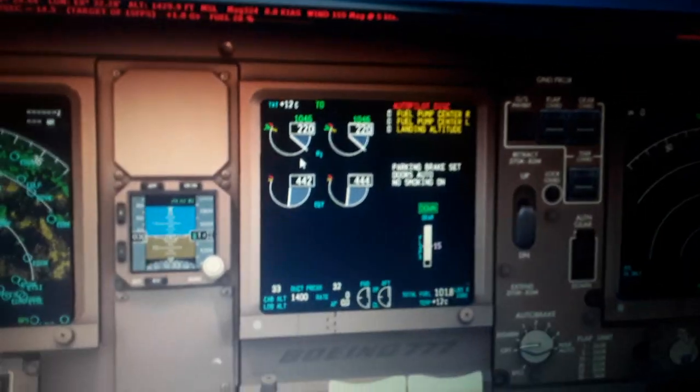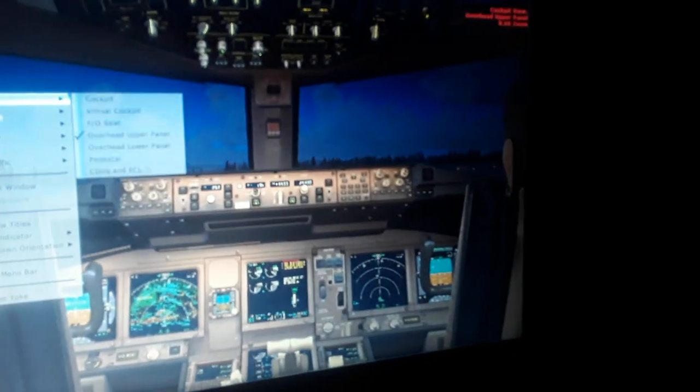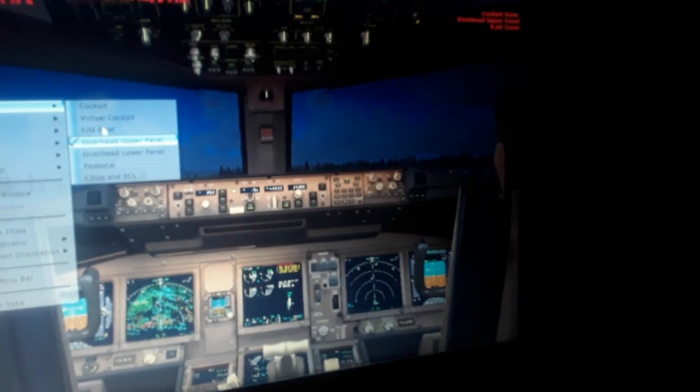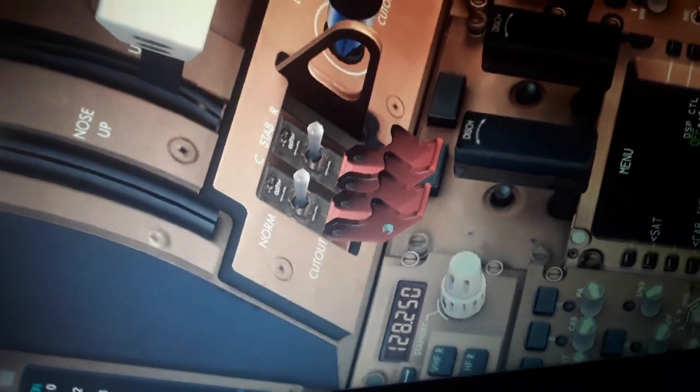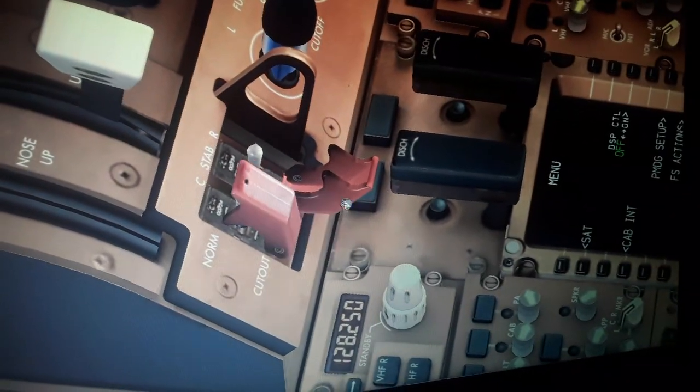You can see the total fuel on board again. So I will show you here. I forgot to mention this. You can see the horizontal trim of the tail, the autopilot disconnect switch here in the control wheel, and also we have the horizontal tail trim normal and alternate. The position of the horizontal tail over here, decrease, is very important for flying, for stabilizing the aircraft, and here, disconnecting the hydraulic fluid from the autopilot.